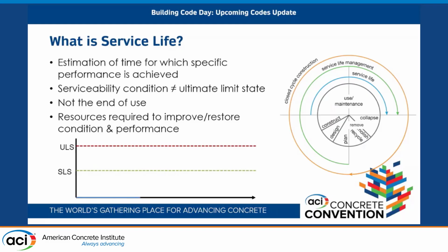So over time, we have a structure where on the vertical axis is going to be how deteriorated it is. For many years, it's going to be working just fine. And then we start to see problems. And then the definition of service life can vary from project to project. In most cases, people would say, well, we have reached a point where the structure needs to have some repairs. If that is the definition that the contract documents establish, that could be the end of service life.